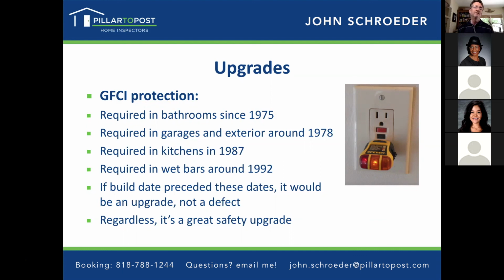An example of this is that, for instance, GFCI protection, those little outlets that have the set and reset buttons, they were required in bathrooms in 1975. And then in 1978, they required them in garages and the exterior. Not until 1987 were they required in kitchens, and then in 1992 in wet bars. So if the build date preceded these dates, it would be considered an upgrade to add GFCI protection and not a defect. But in any case, it's a great safety upgrade, so I always note it in my reports because it's not terribly expensive either.